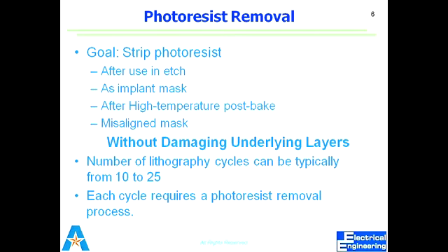And one more thing: when you are dealing with more than one photolithography process, while working on the second or third level, you always keep in mind that you don't damage the underlying levels, meaning the first step or the second step process. You need to be very careful while etching or patterning the device, so that whatever etchant you are using is not sensitive towards the surface underneath, so that you don't damage or destroy the first layer of the process.